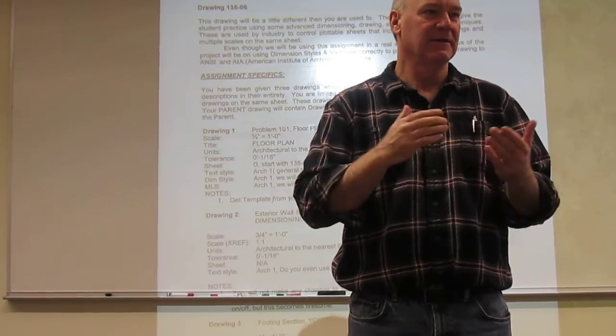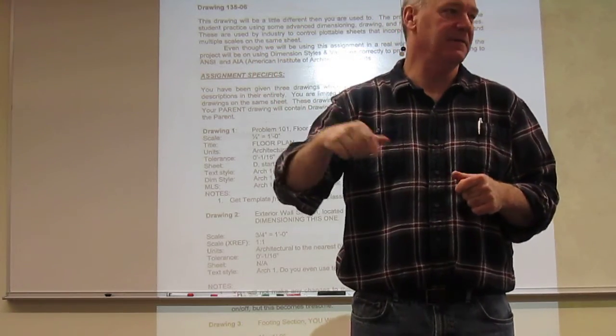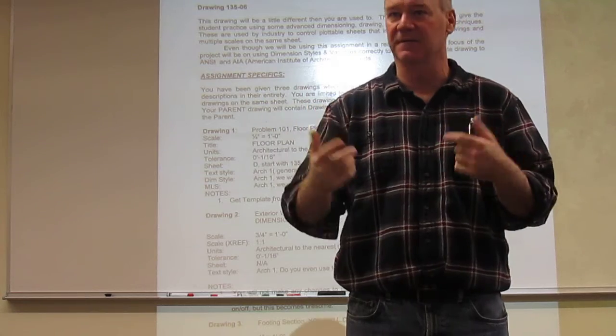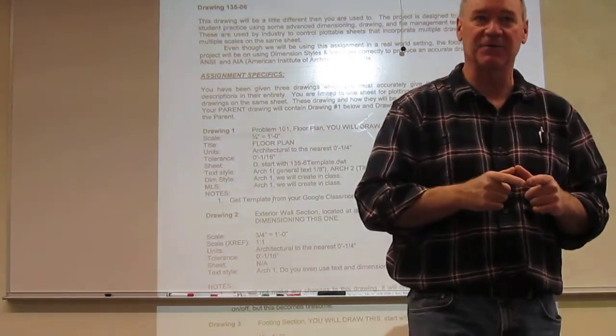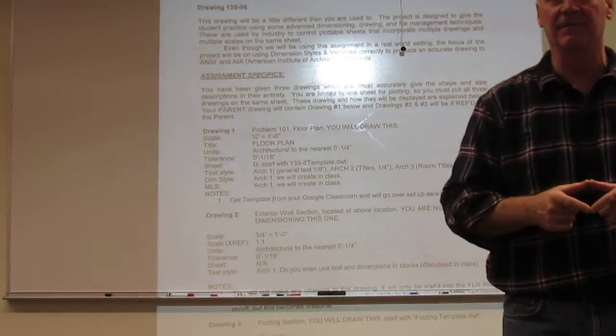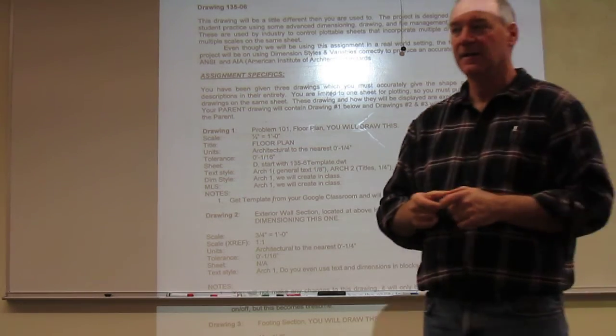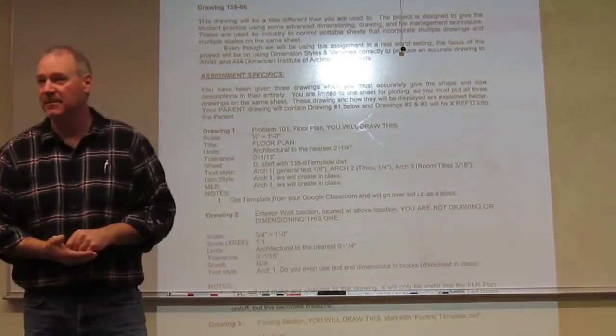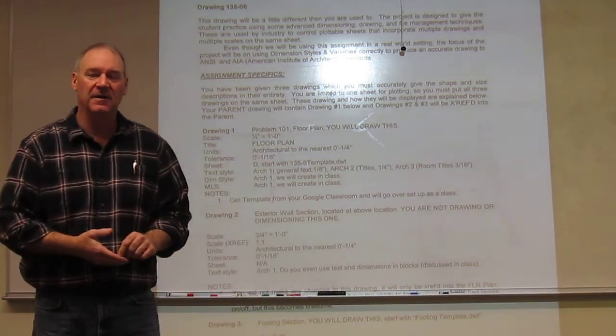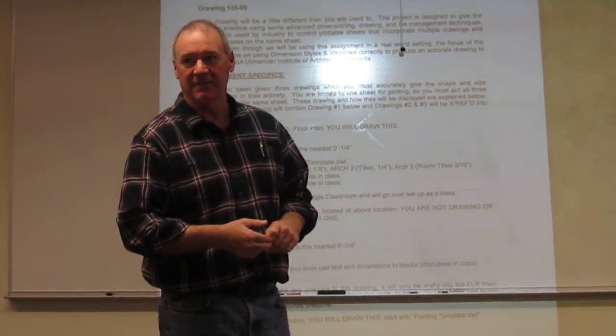My text that is on it is always an 1/8. My gaps are 1/16, 1/8 on extension lines. All of these criteria still need to be on a sheet regardless of the scale. Therefore, when we do multiple scales on here, you're going to want to make sure you're paying attention to dim anno and you are calculating the DSFs for these scales.